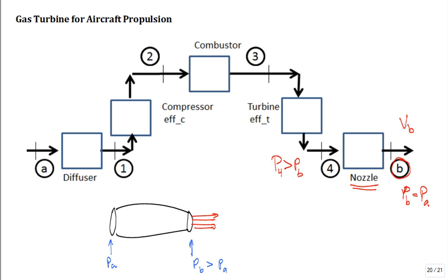And so if you have the same mass flow rate, m dot, through the system, I know we add a little fuel, m dot of the fuel, so the mass flow rate of the exhaust is going to be the mass flow rate of the inlet air plus the mass flow rate of the fuel, because mass is conserved. But most of the time we just neglect the mass flow rate of the fuel, and it's negligible or close enough to negligible. We have other approximations in this.